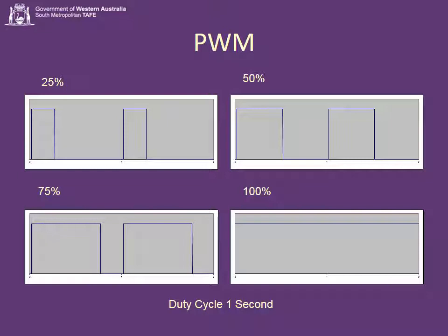This is how we control heaters, such as electric duct heaters, so that something which is normally and traditionally on-off can be controlled to a percentage. And because the heater is quite a large chunk of metal, you're not aware of the flickering, because it evens out. So we use this to control electric duct heaters.